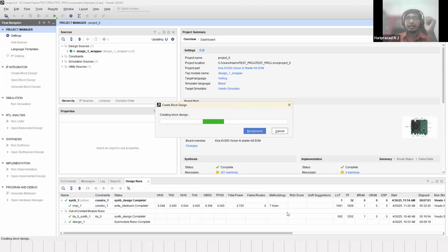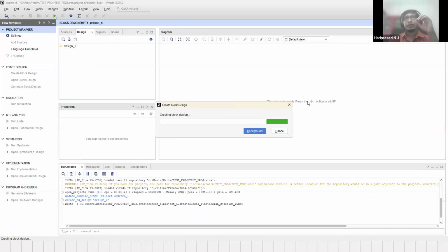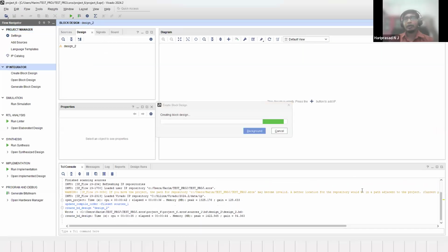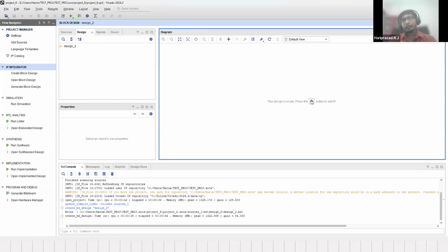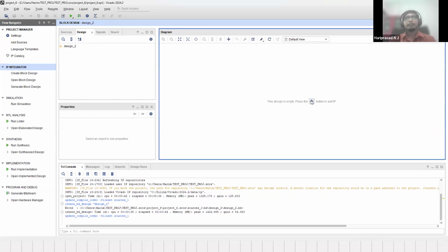In the previous case, if you see what we had synthesized yesterday, after synthesis it took only one LUT and 32 flip-flops for the simple counter logic. Now, with the same counter logic, I will add the MicroBlaze, so you can see the resource difference, how much it is taking, because this processor is consuming your flip-flops and lookup tables. I'll show you how you can integrate this MicroBlaze processor.